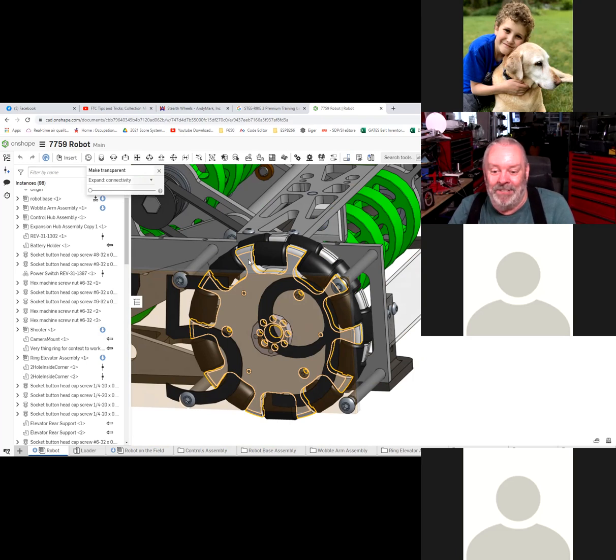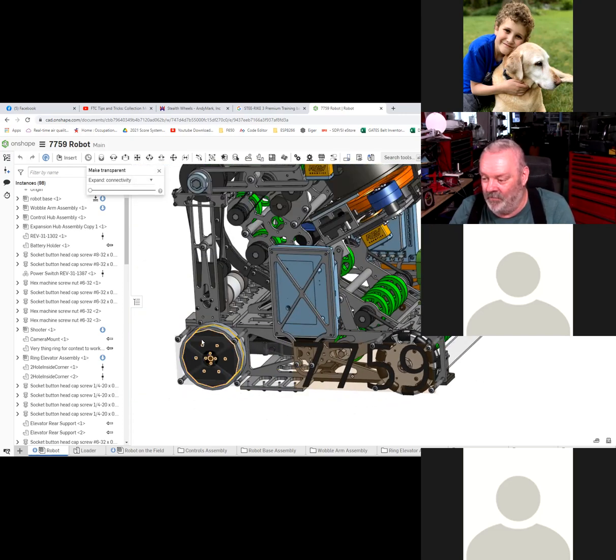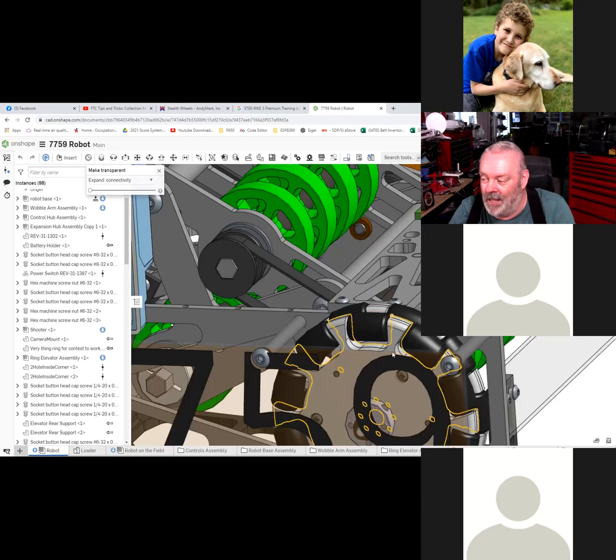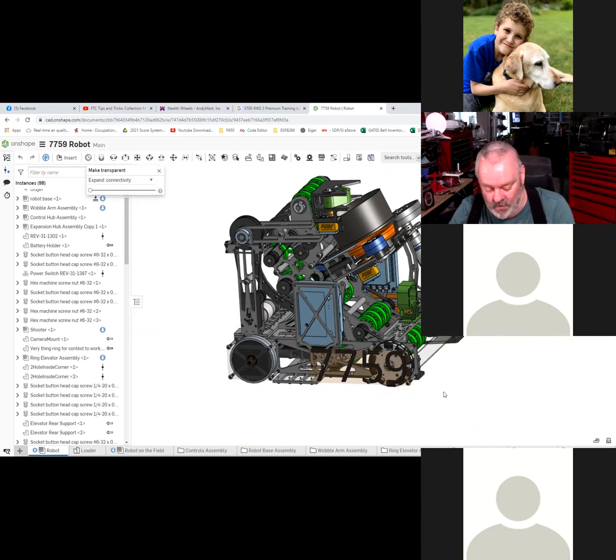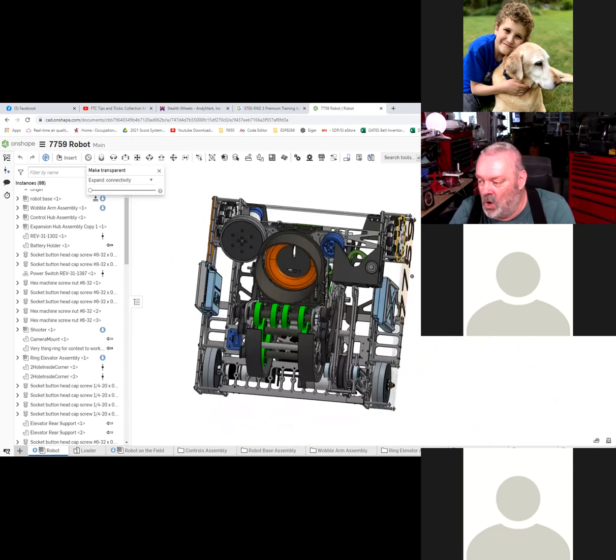It depends on the contest that you're doing and what your design parameters are, right? The upside to this is that if you're using this differential thing, these wheels allow the robot to slide sideways. So when you go to turn, there's no coefficient of friction in this direction. These wheels will slide very easily left and right. And so if that's what you need, it's not a bad option.